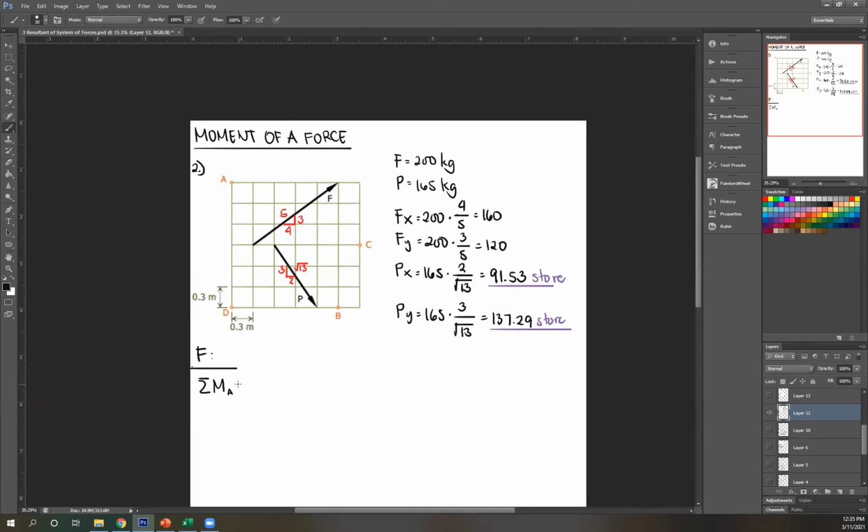Okay, so let's start with Fy. Now, again, the next step is to choose the position of your component. Usually you do that in the way that is most convenient, wherein one component cancels out. I'm taking moment about A, so in order for one of my components to cancel out, I can take my components here. It's the same thing; again, you can get it here, here, here, and so on. Just choose the most convenient position. I'll take it here.